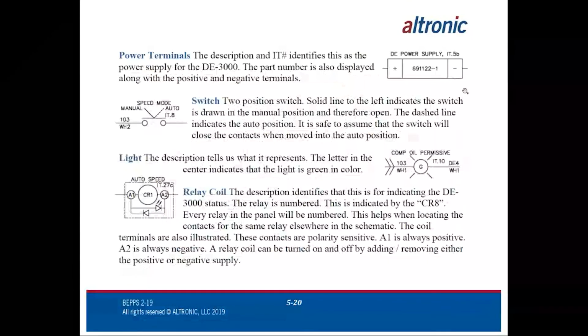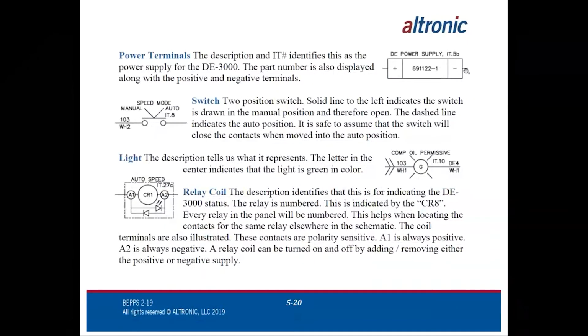So a lot of times when we have products in the panel that we're just trying to get power to, we'll draw them as rectangle blocks. We'll show the negative side, generally with a 102 coming into them. 102 in an electronic panel is always battery ground. We'll show whatever power is powering up the positive side of the device.